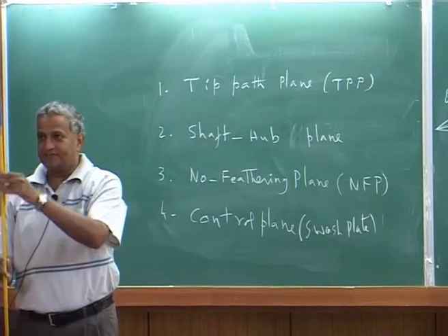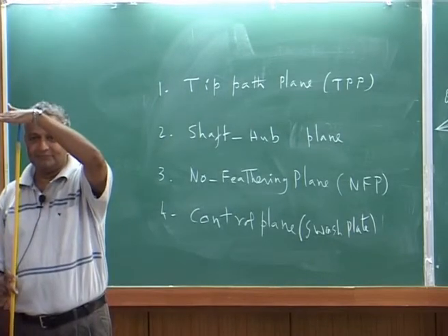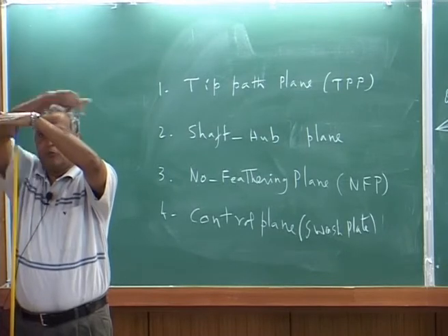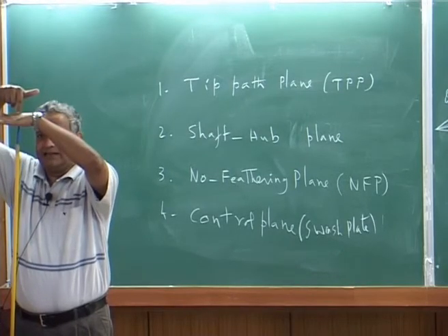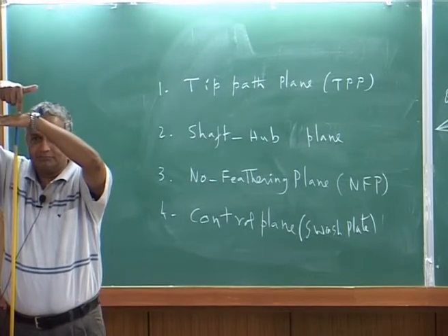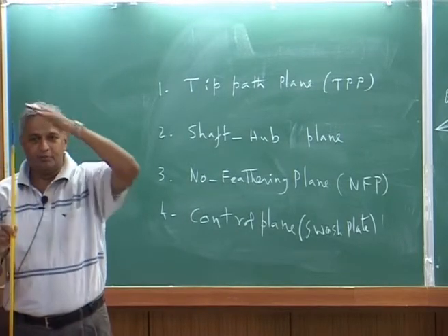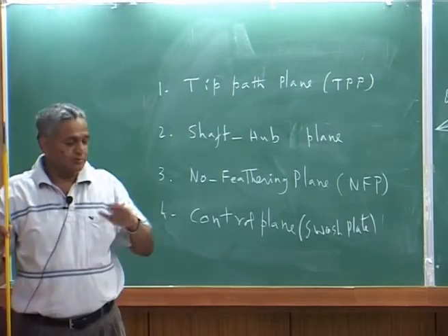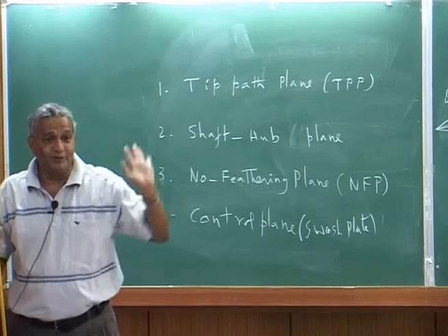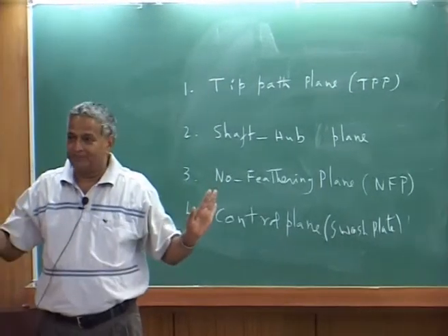So this is the shaft, this is the hub which is 90 degree. So you define what is the velocity in the plane of the hub, normal to the hub, that's all. In the plane of the hub is your forward speed, normal to the hub is you say inflow, that's all, okay.